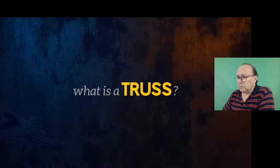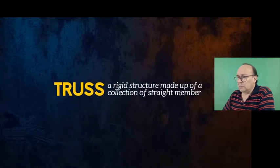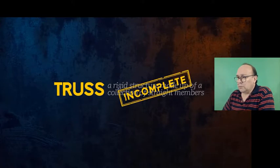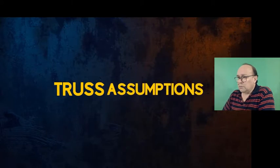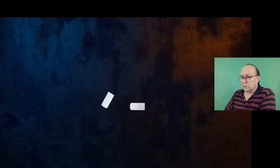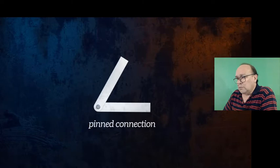So what exactly is a truss? It is essentially a rigid structure made up of a collection of straight members. But that's not a complete definition. There are two important assumptions we need to be able to make for a structure to be considered a truss. First, we need to be able to assume that all of the joints in the structure can be represented by a pinned connection, meaning that members are free to rotate at the joints.